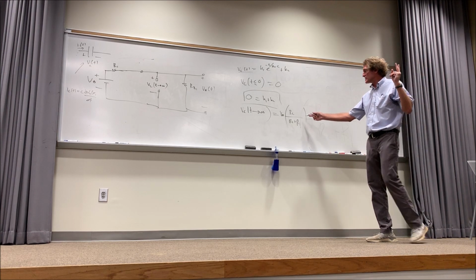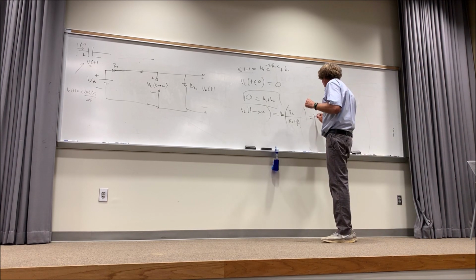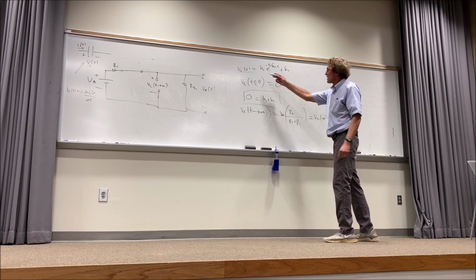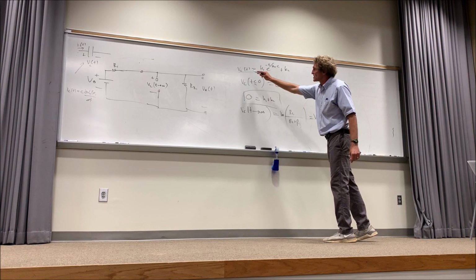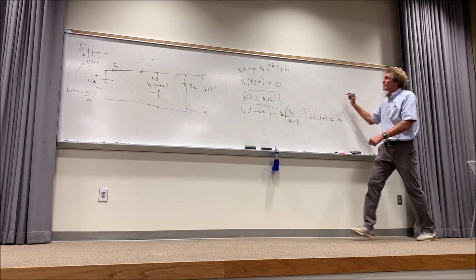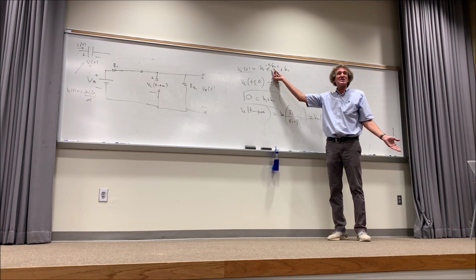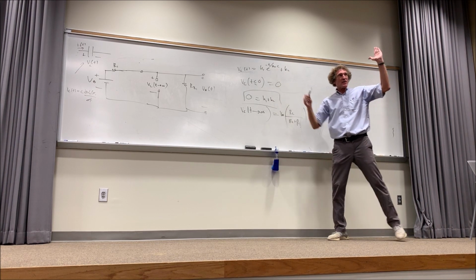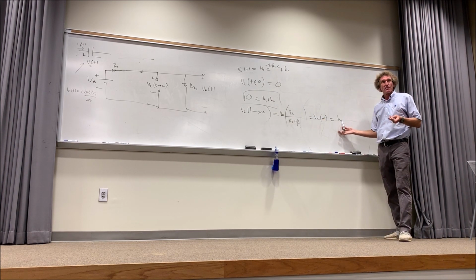Look, say this is VC, I'll just call this VC of infinity here. You all see that? What happens to this equation when time goes to infinity? That's equal to just K2, isn't it? K1 is 0 because e to the minus infinity is 0. How many see that? So the voltage at infinity across that capacitor is K2.